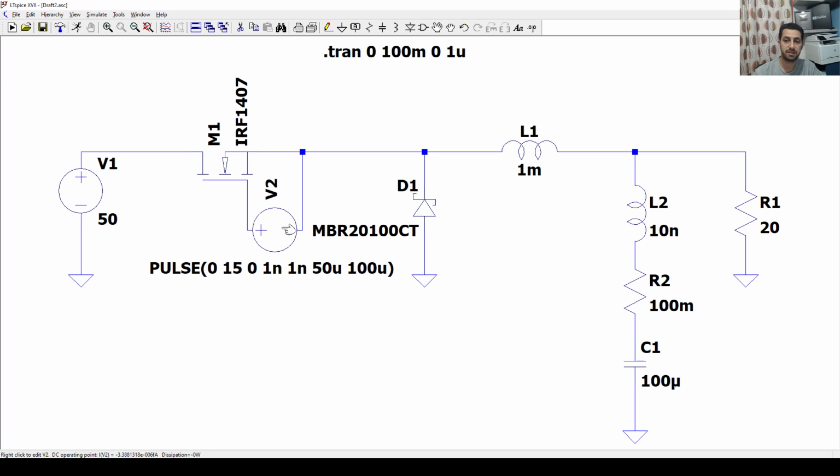The next step is that the PWM generator here practically doesn't exist like this. It's just a signal generator, and maybe we get that PWM signal from a microcontroller or another device. But between our PWM generator and our MOSFET, we want a gate driver, and that gate driver is to speed up the switching and to make sure that the MOSFET goes into saturation or cutoff very quickly. That will reduce the switching losses and also reduce the thermal stresses on our MOSFET.